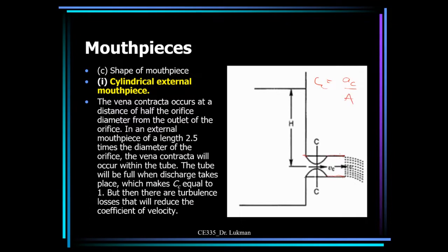This is the area of the orifice, okay. So this is the area at the end, okay. So if they are equal, this will approximately equal 1. In practice, you may not get exactly 1 because you still have shear stress, frictional force acting, okay, but it will be maybe 0.98, 0.97, which is approximately equal to 1, okay.